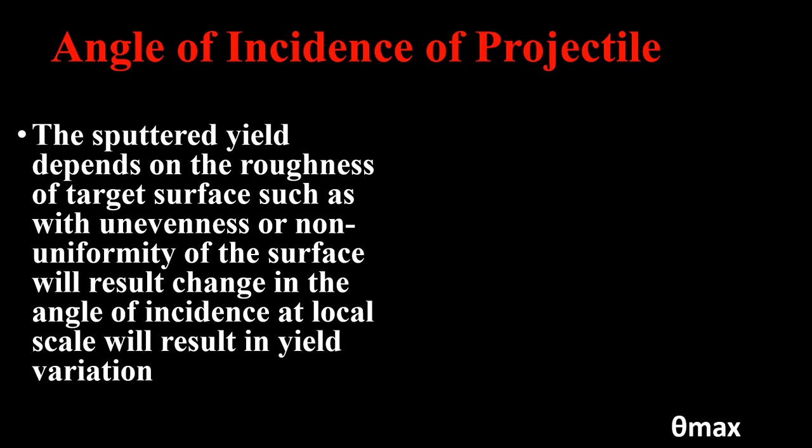But an interesting fact to note is that if the surface of the substrate is of a different shape, the deposition rate will be the same, but the adhesion with the surface will be different, okay? If the surface is more rough, or has higher features at atomic scale, it will have a higher surface energy and get better adhesion.